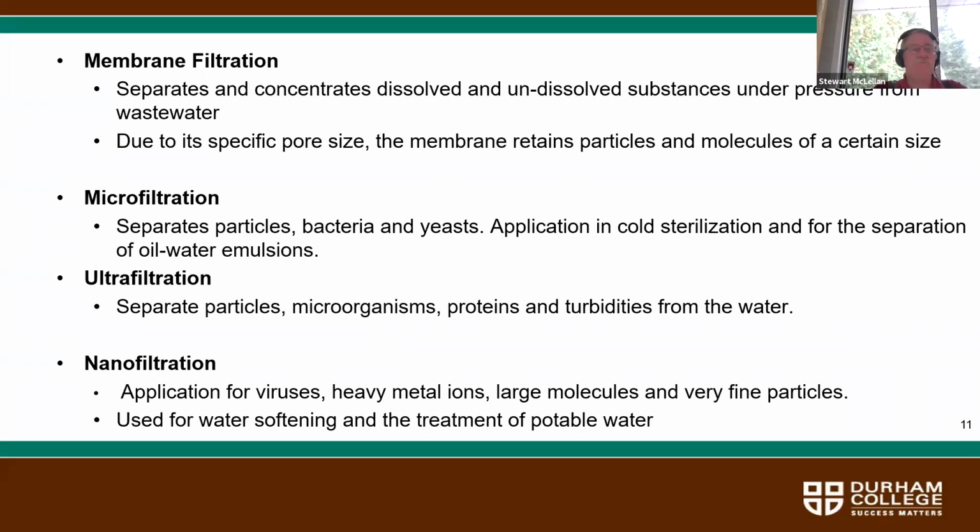Okay, membrane filtration separates and concentrates dissolved and undissolved substances under pressure from wastewater. Due to its specific pore size, the membrane retains particles and molecules of a certain size. So the key there is that depending on the pore size of the membrane, these membrane filtration systems can be designed so that they're not only removing suspended solids, but they are also removing large molecular size dissolved solids.